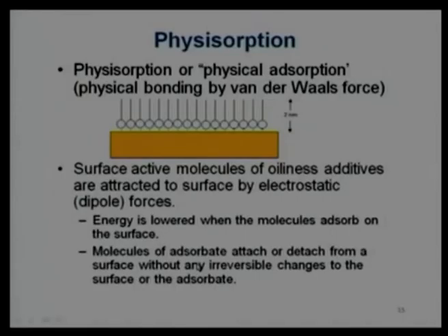However, we say many times that attachment and detachment is a continuous process, but nothing is going to get damaged if it is under normal load and normal speed. We are not talking about severe load and severe speed. In that situation, it will not get damaged. It will only detach from the surface, and after some time it will come back and attach. So, it is a continuous process. We need not change the lubricant oil frequently if that is the mechanism.